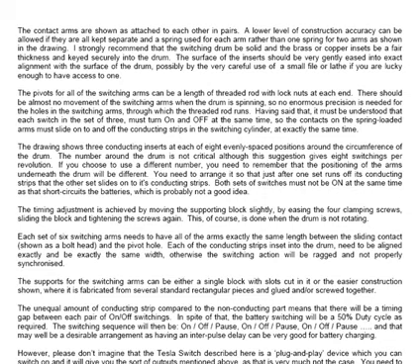Although this suggestion gives 8 switchings per revolution, if you choose to use a different number, you need to remember that the positioning of the arms underneath the drum will be different. You need to arrange it so that just one set runs off its conducting strips, and the other set is on the insulating section of the drum body on the other side. Both sets of switches must not be on at the same time, as that short circuits the batteries, which is probably not a good idea.